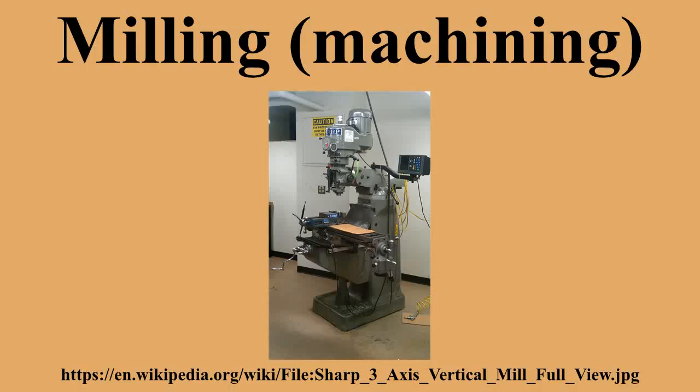The cutting action is shear deformation. Material is pushed off the workpiece in tiny clumps that hang together to a greater or lesser extent to form chips. This makes metal cutting somewhat different from slicing softer materials with a blade. The milling process removes material by performing many separate, small cuts. This is accomplished by using a cutter with many teeth, spinning the cutter at high speed, or advancing the material through the cutter slowly. Most often it is some combination of these three approaches.